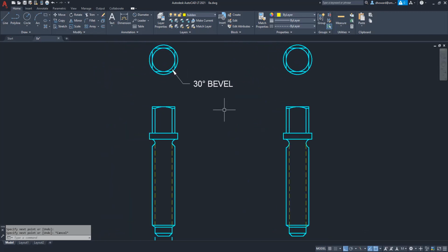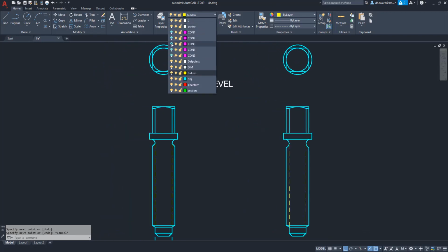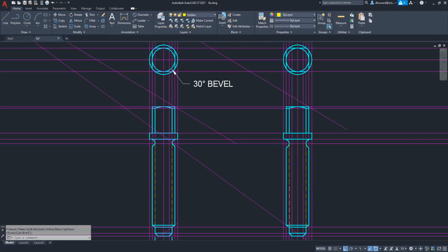So if I turn my construction lines back on, see what I'm talking about here. This diameter and then the inner diameter, which is a 1/16 inch in. So it would be this circle here to here. So that represents the 3/8 diameter down here. And then you could offset that in another 1/16 inch to show you this smallest flat face on the bottom.